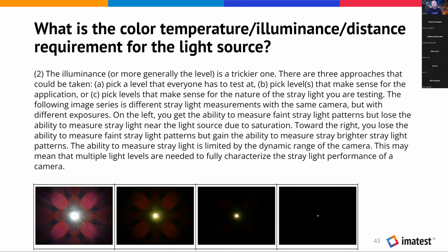By doing this kind of comprehensive mapping of that space, the goal is to identify certain angles of light coming into the system that are problem areas that could lead to misdetections or false detections, which could impact your computer vision performance and the safety of your camera if it's a safety related item. That's the rationale behind this super comprehensive test where we're testing thousands of different points, to see where those failure modes are.